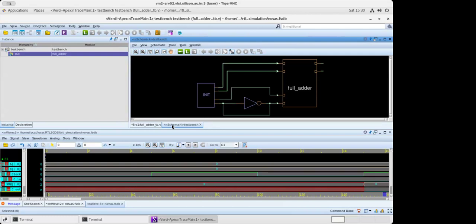But if you want, you can do it for your normal RTL also. In the first command, the VCS command which is commented, you can use that, fix the file name there, try it there also, and then open Verdi. The code will be in one window, select, and it will give you this kind of waveform.